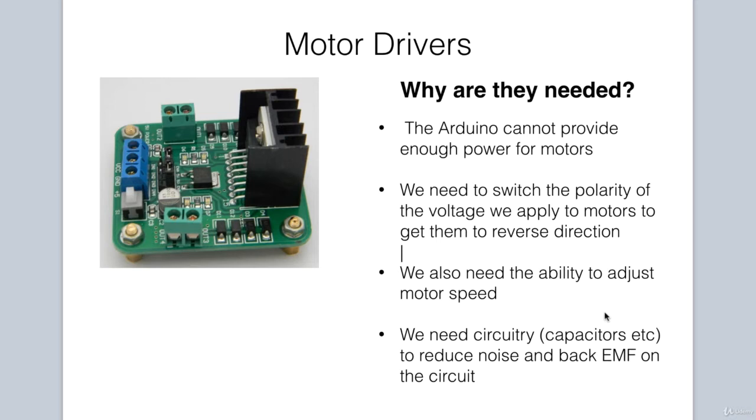First, let's discuss the importance of motor drivers and why they are needed for our project. The maximum power that the Arduino can provide is around 100 milliamps or 0.1 amps, whereas some motors require several amps to operate.